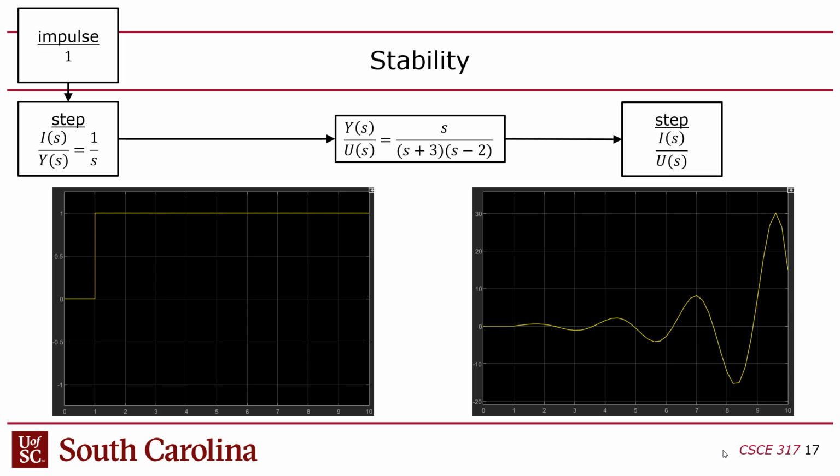And the idea is when you have a transfer function or an agglomeration of transfer functions that are convolved together, ideally, if you have a bounded input, finite input, you should get finite output. But I mentioned that in practice, even a physical system or a control system is not going to explode to infinity. I mean, everything has its limits. But the idea with stability criterion is that you want the system to stabilize or to converge on a set point of your choosing, right? That's the idea of stability.